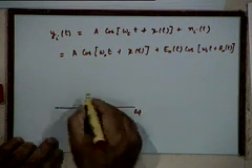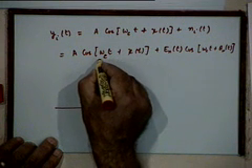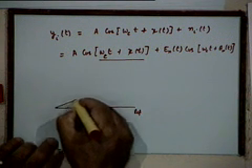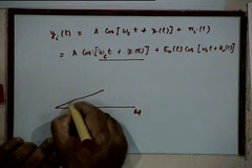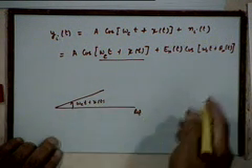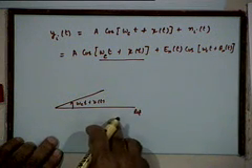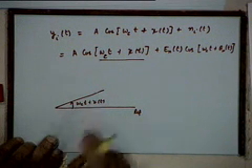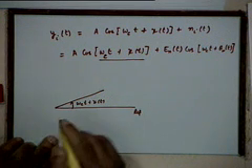At the time instant t, what is the instantaneous carrier phasor? Omega ct plus psi t. Let me denote that by this. If you are assuming that the whole system is rotating at omega c radians per second, then you can simply write psi of t. Otherwise you write omega ct plus psi of t.